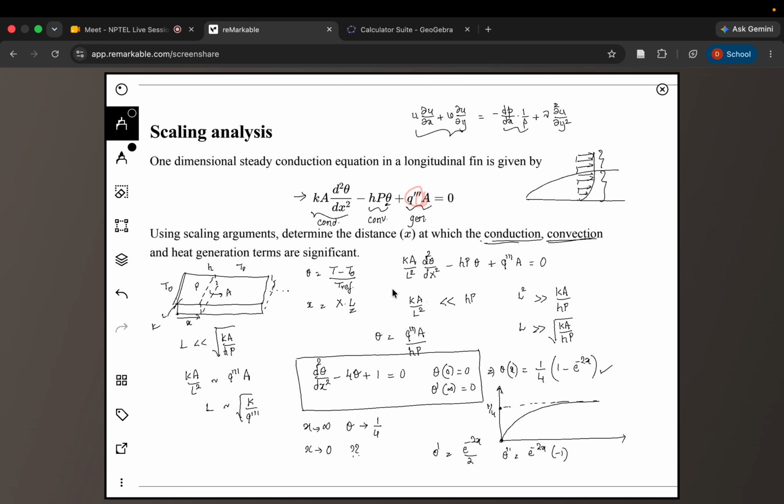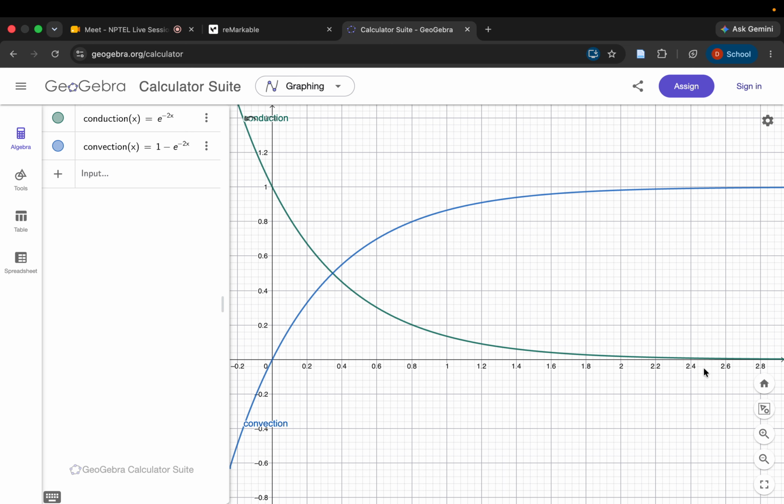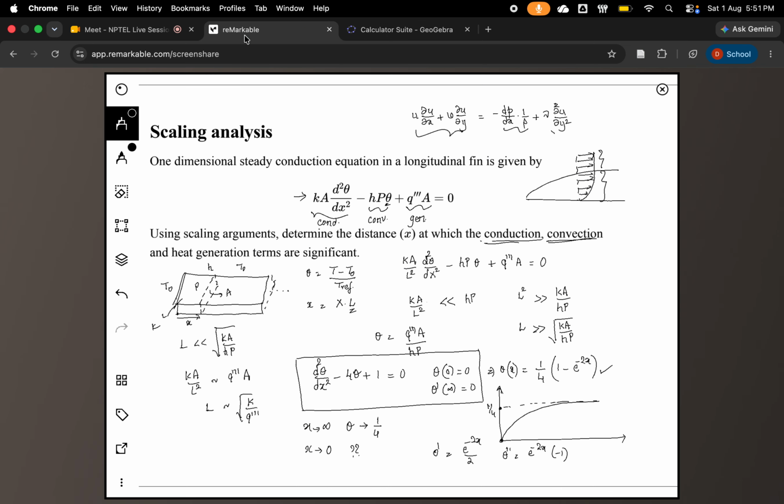So what we are trying to understand now is the same thing that you are seeing in this graph. Very far from it, we will see that the conduction term is actually negligible, which in this particular case is this term. So very far from the wall, you have d square u del y square becoming 0. So the effect of this will become 0, and it is only inertia versus pressure. These are the only two important terms in the momentum equation. And when we go close to the wall, it is the convection and conduction. These two play a major role. Which essentially means inertia is balancing my viscous forces, and the effect of pressure will actually reduce.